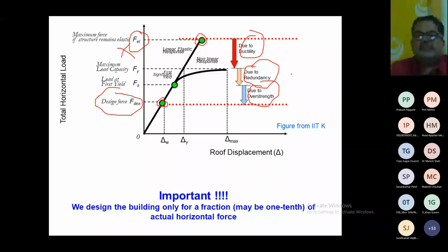But suppose 4 legs are required for the table to remain stable for equilibrium, and I'm adding 2 more legs. That will provide a redundancy. Such redundancy we have in the real structure.